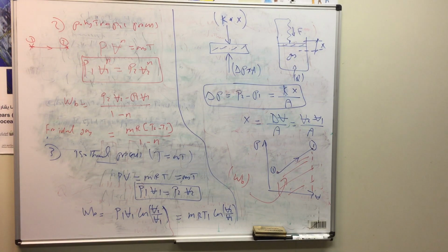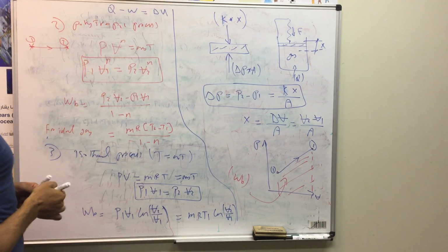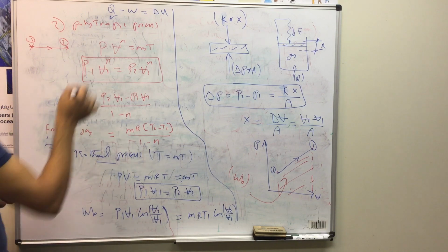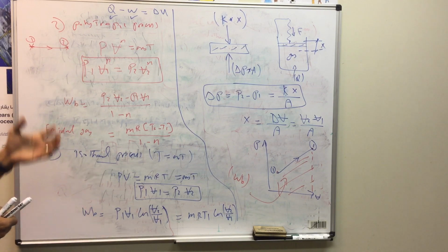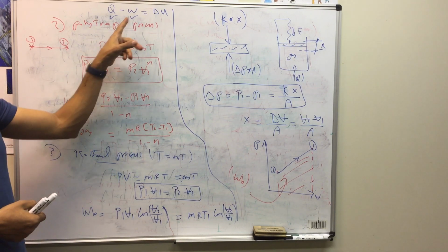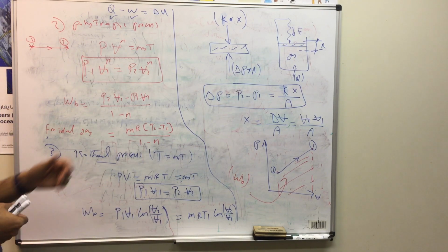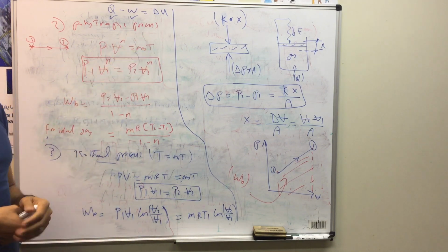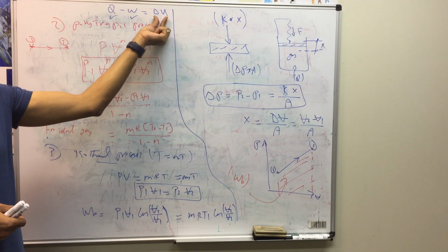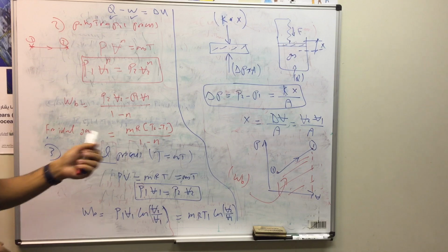But get back to the first law of thermodynamics equation. We said for a closed system, heat transfer Q minus work equal to delta U. We have considered this term, heat transfer. We have considered this term work, which is any other kind of work like electrical work, or if you do have a paddle wheel or something, plus the boundary work. And we have considered the special cases, how to calculate the boundary work when we do have a piston cylinder device and one of the boundaries is moving. We are left actually for this chapter to be done with how to calculate delta U. So, let's consider this.